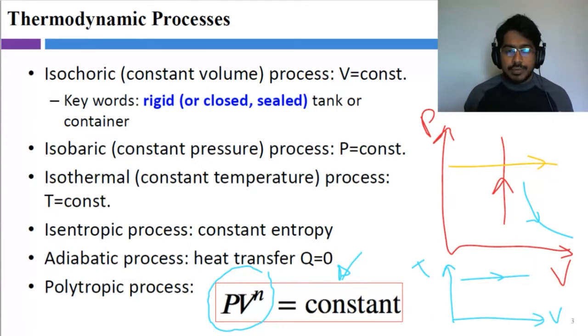If it is isothermal or isobaric or isochoric, we can use that feature to solve the questions rather than treating it as a polytropic process. But there are some processes with no other special characteristic like constant pressure or constant temperature. In such a situation, if the process is polytropic, then the polytropic equation is very important, and it makes our life easy when tackling the problem, right?